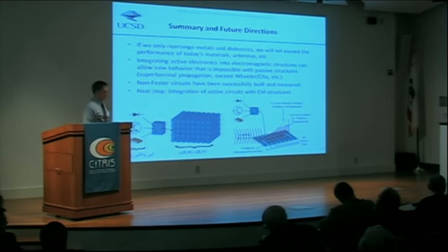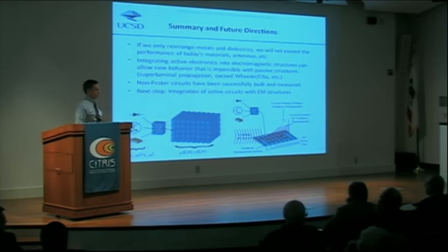Right, so the same issue is true in antennas, and that's why when we want to show an improvement in performance, we can't just show a match having a broader bandwidth. We have to show a real improvement in signal to noise or a real reduction in noise floor. And in fact, a couple of people have shown that so far. There's plenty of other issues that I didn't get into as well.